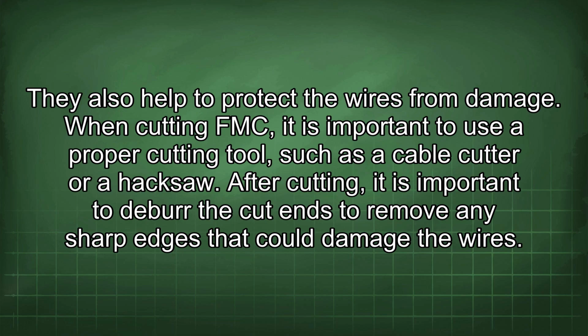When cutting FMC, it is important to use a proper cutting tool, such as a cable cutter or a hacksaw. After cutting, it is important to deburr the cut ends to remove any sharp edges that could damage the wires.